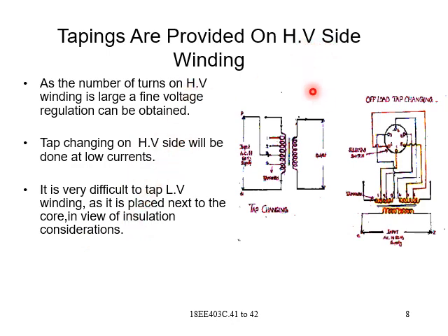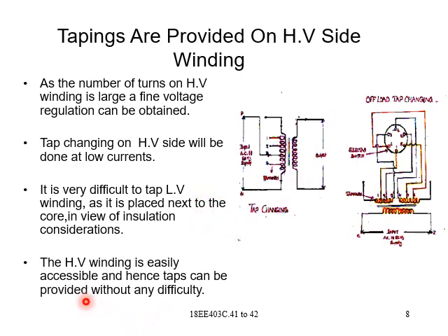The tappings are done only on the HV. The HV winding is easily accessible and hence taps can be provided without any difficulty.